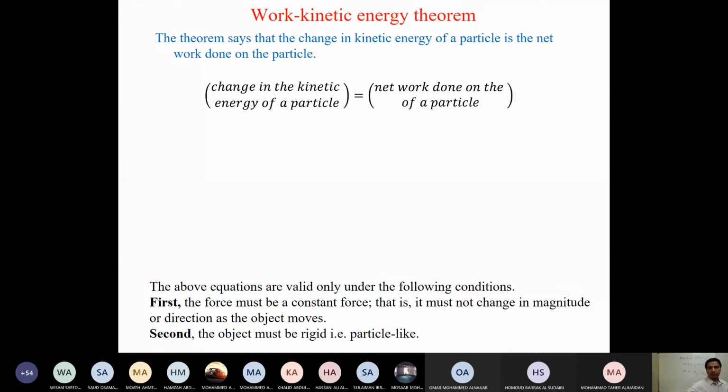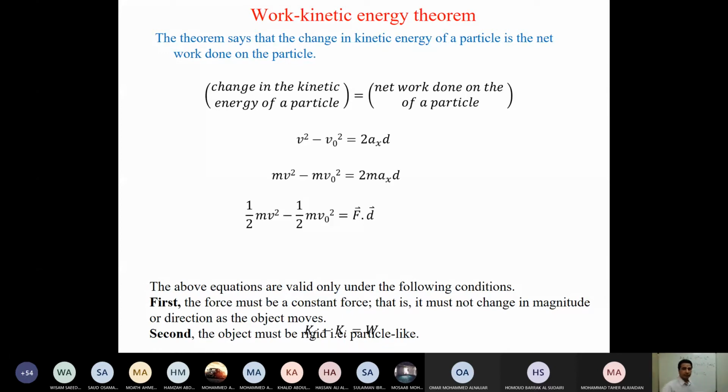But we should be a little bit careful when we are applying all these formulas. First of all, you know that this equation was derived specifically for the constant acceleration case. So the work energy principle in this form, as we are using it without integration, will only apply to the constant acceleration situation. That's one thing. Second is that you are not considering any non-rigid objects.